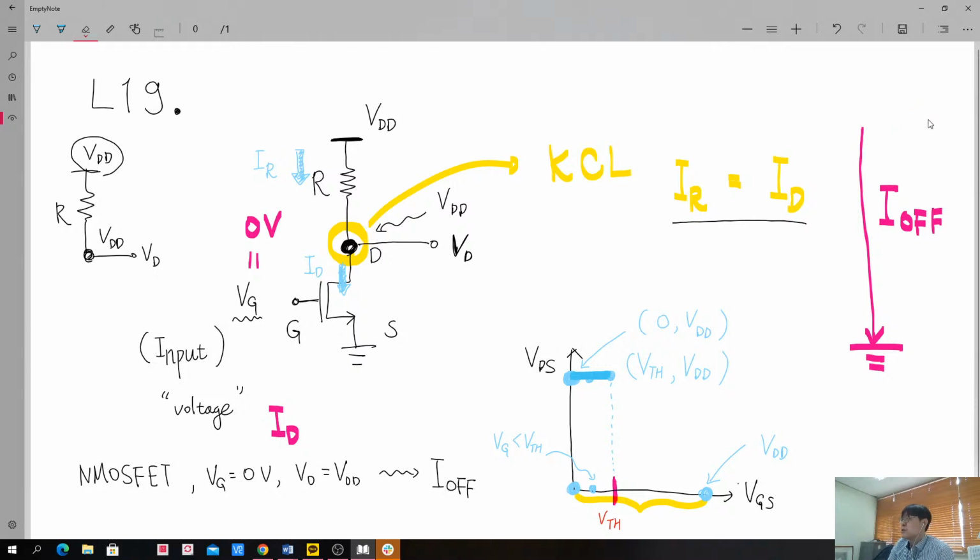No difficult discussion up to now. Then now let's go to beyond threshold voltage. So it will be quite interesting. Yes, now we have here. Since gate voltage is higher than threshold voltage, now we have to consider either triode mode operation or saturation mode operation.